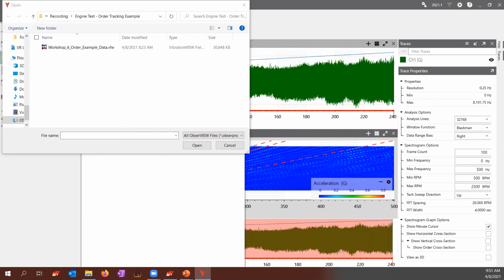And of course, that's going to be much more representative of the country as a whole, right? So unfortunately, there's no clear answer, but in terms of test acceleration, we generally say you don't want to go much more than 10 times. So that MIL standard test was roughly about 10 times acceleration, but it depends on the product. It really depends on at what point do you start damaging the product almost as a shock test instead of multiple cycles, right?